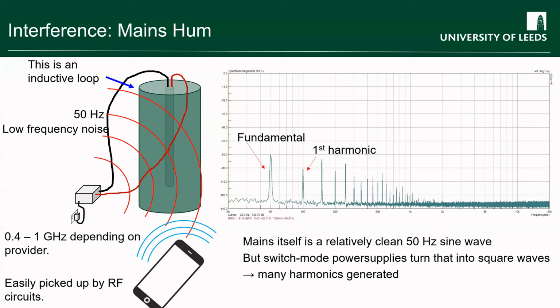And then, of course, the other end of the spectrum, you have various RF sources going on, mobile phones and Wi-Fi being the most common examples. But also, you'll find other parts of the electronics are going to be driven. So, of course, typical microprocessors run at a few gigahertz these days. So, again, that's a rather nice little RF interference source, because you have a digital computer turning itself on and off with a clock, and the clock is running at up to a few gigahertz. So there are all of these kinds of human interference that you need to think about.